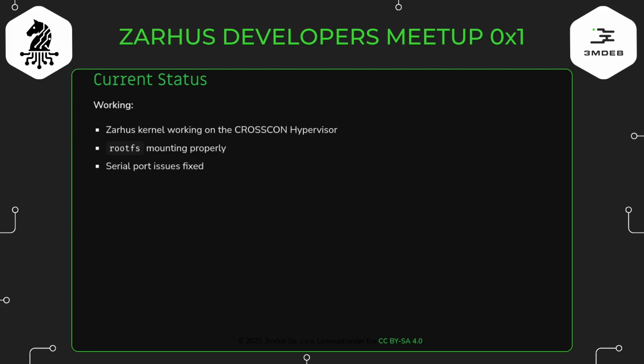There were a lot of issues with the serial port in this integration. Mainly, I was initially very confused because the correct port has to be specified in the device tree file, but with Buildroot it does not. So that took me a little bit to find out. And there's also another more esoteric issue which we haven't been able to quite pin down yet, but I will show you that later during the demo. And we have a working Linux environment. So anytime we want to add a new tool, we can just add a Yocto recipe for it, and it's way easier that way.